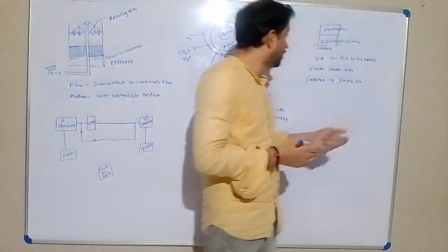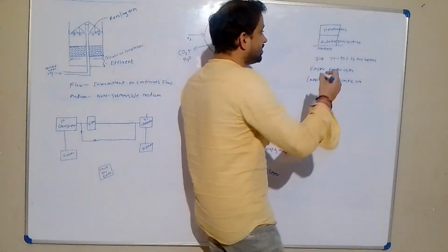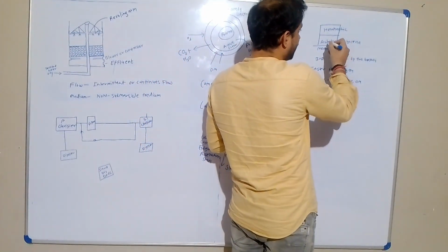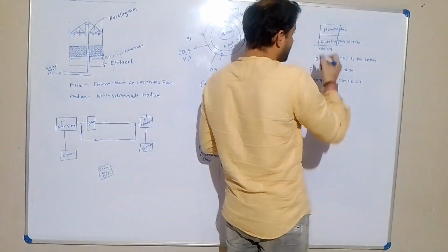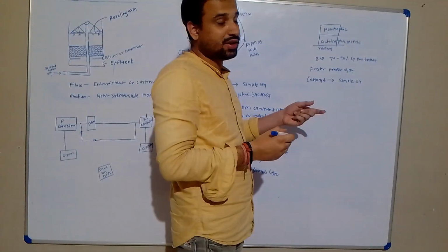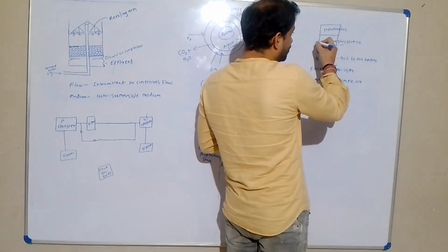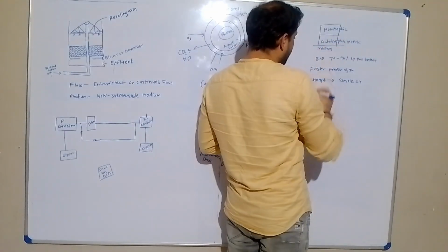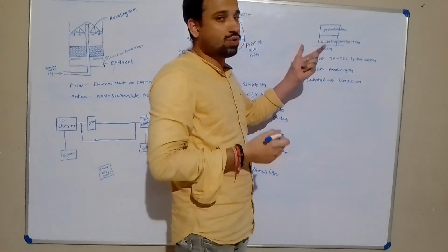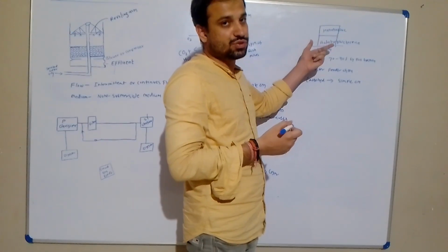And the autotrophic bacteria, where the scarcity of food takes place, endogenous respiration starts and depletion of O2 is more in this layer. This is the lower layer which is attached to the media. So oxygen is not present here, oxygen is not present, so the availability of O2 is deficient in this zone.